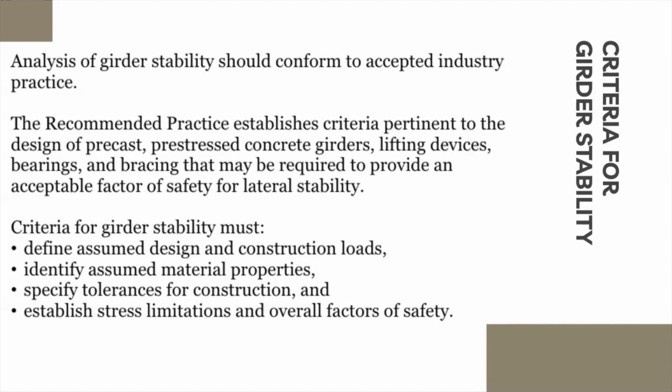The four main criteria for girder stability must include defining the assumed design and construction loads, identifying assumed material properties, specifying tolerances for construction, and establishing stress limitations and overall factors of safety.